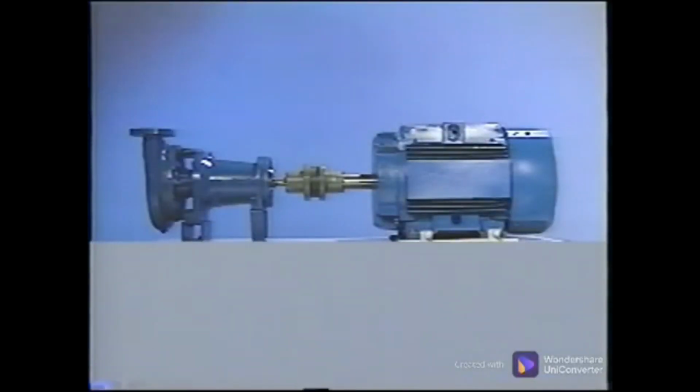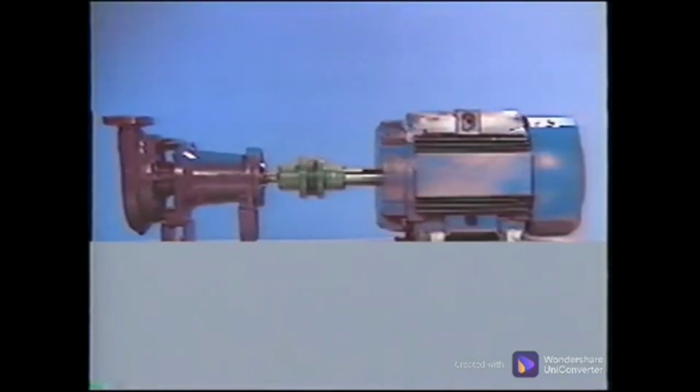Thermal growth is the change in the physical size of the machine from the offline condition to the online condition. If thermal growth is not taken into consideration during the alignment process, the smooth running condition and restart may become a rough, vibrating machine when it returns to its normal operating temperatures. Most machinery operates well above ambient temperatures, and the actual size of the machine will increase as the temperature increases. This would not be a problem if the machine grew the same throughout, but that is seldom the case.